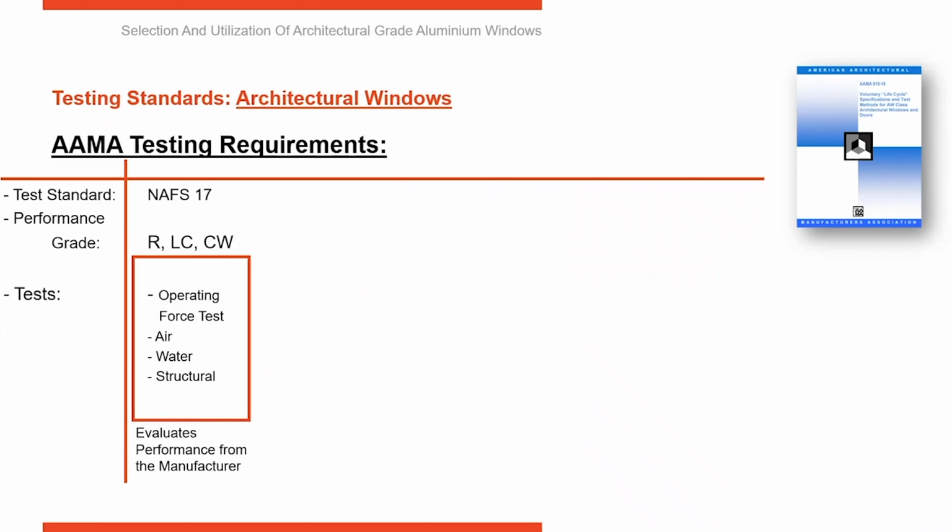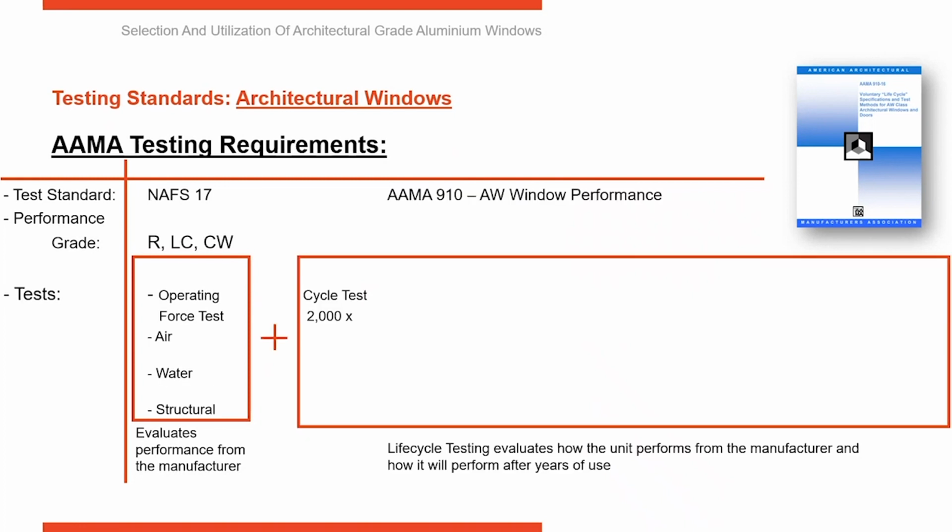Then after that, we apply misuse testing. So I mentioned university buildings, hospital buildings. Let's take a university, for example. Students are opening, closing windows. They're slamming them closed. They might be pulling them closed. They don't realize, but there's a stick in the window and it twists the frame, or they're pushing it open and one of the latches is still closed, so they're twisting the window.